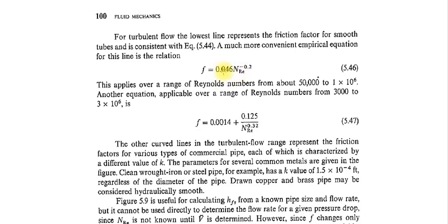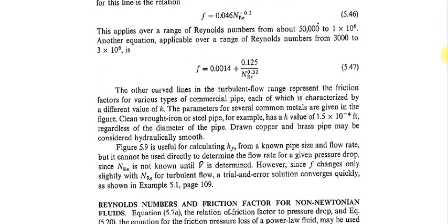There is no theory behind these formulas. Different people have done experiments at different Reynolds numbers, calculated the friction factor experimentally, and then fit the data to equations to get these correlations. So you can either use the Moody chart to calculate the friction factor in turbulent flow, or use the empirical formulas.